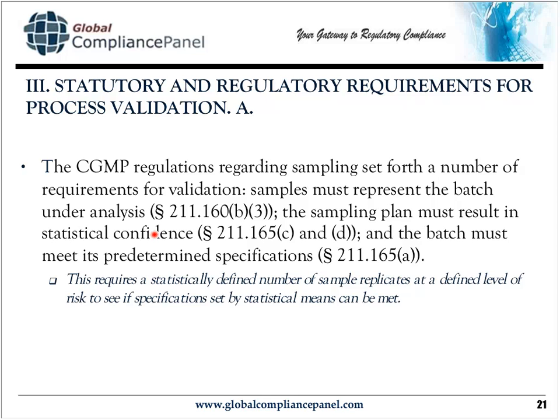And also that the specifications you set here should have been set with the variance in mind, and which would require at least a tolerance interval calculation. And this sort of thing, statistically defined number of sample replicates at a defined level of risk.